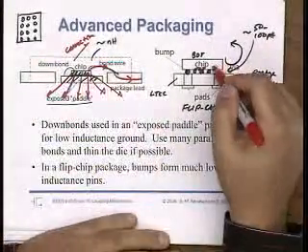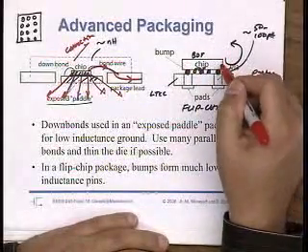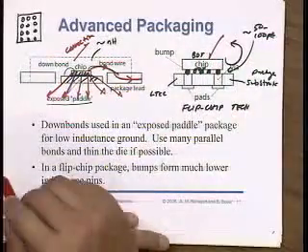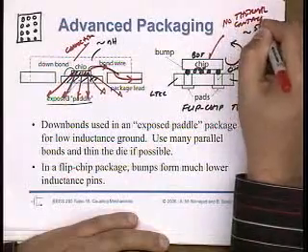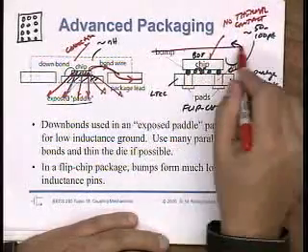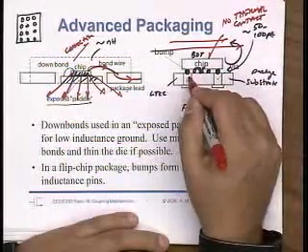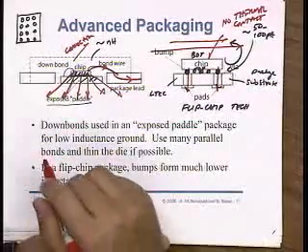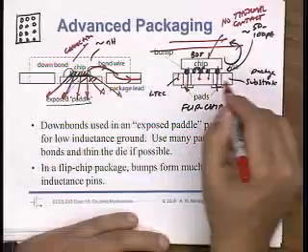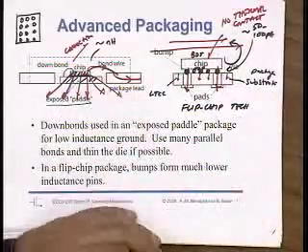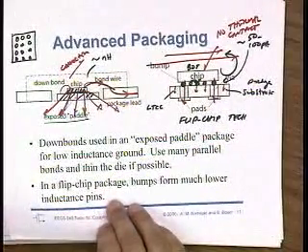and keeps the temperature low. Over here, even though I have this nice conductive silicon, it doesn't make thermal contact on this side. So there's no thermal contact. The only way to lose heat here is through, let's say, convection or radiation loss. Most of the heat has to be pulled out through these vias, and maybe some of it through this package. And so this die will run hotter than this die over here. Okay. Questions or comments?